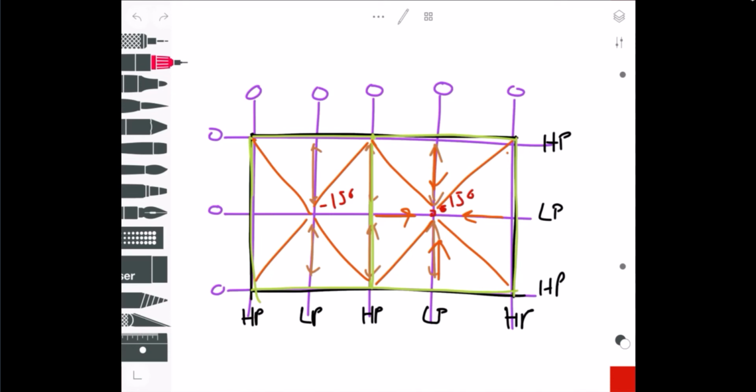drainage points. So usually the cheap option is, if you look up at the parapets of buildings, there will be a hole in the parapet. Let me find a nice bright color here. There will be a hole in the parapet, maybe there, there, there, there, there, and there. It's usually just a little rectangle, like maybe 200 millimeters wide by 450 long or something like that.